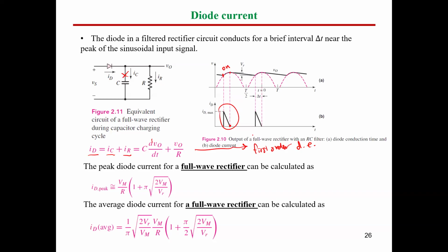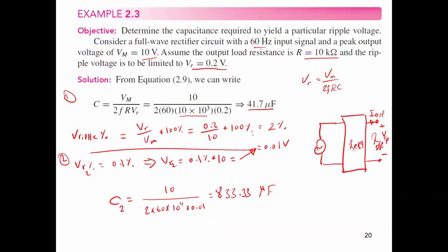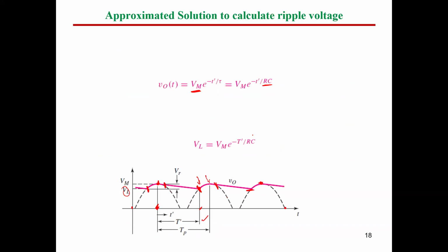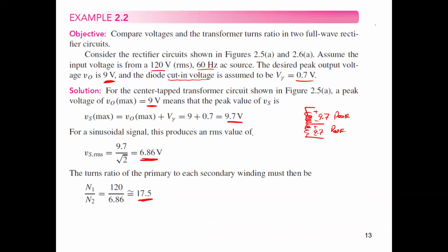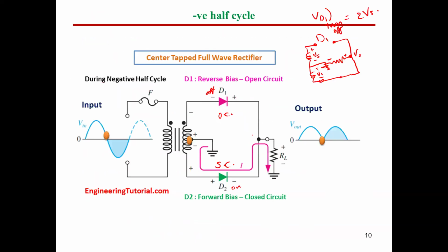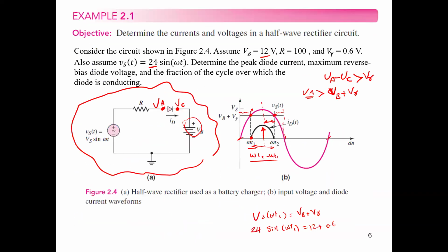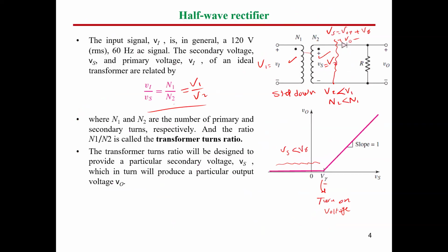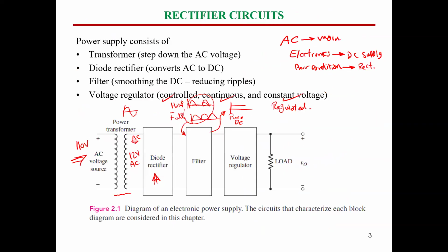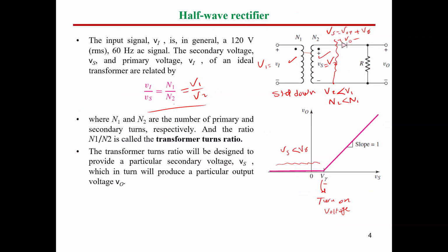Why? Simply, if you go to the circuit without a capacitor, say for the simple half-wave rectifier, let's have it also for just the resistive load, like that. What can you see here, guys? The diode current is the same as your load current, correct?